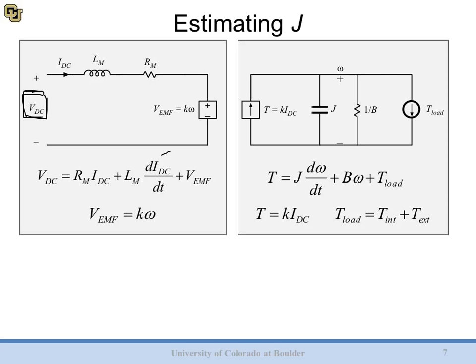What does that mean? Well, if we have time down here and VDC up here, and if we just go along, here's our voltage, and then at some time we just turn it off. What we should see is our voltage starts to slowly drain away and ramp down as soon as we turn it off. When you turn off these supplies, they simply open circuit their output, and so we end up with an open over here.